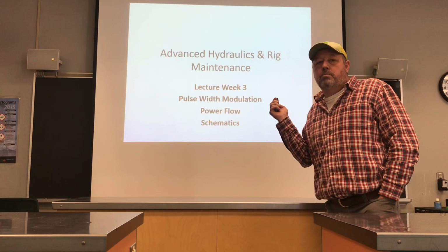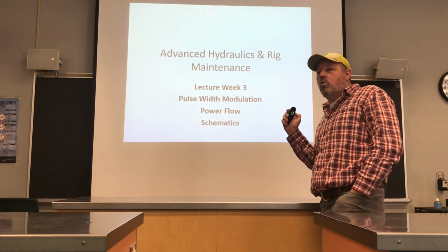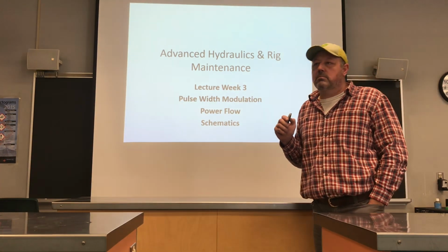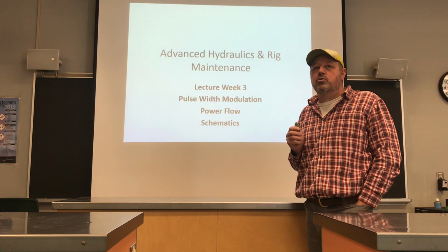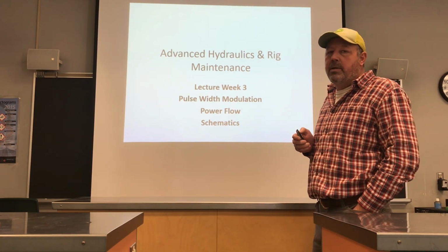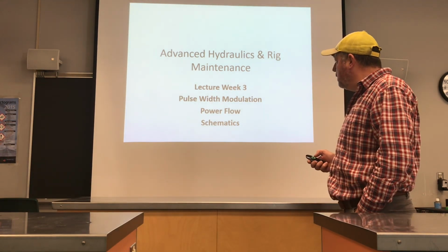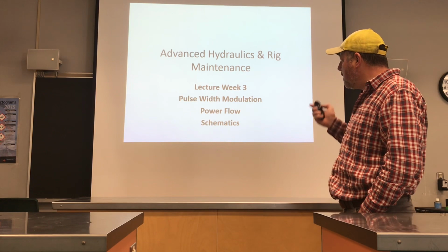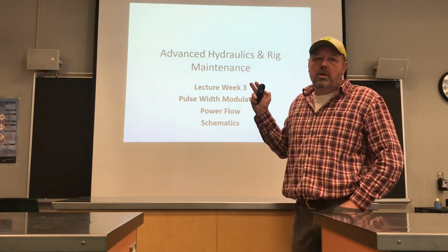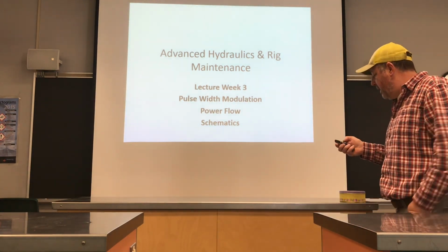Basically, we use pulse width modulation or duty cycle in order to modulate or proportionally control how fast or how slow an implement or a cylinder moves. We'll talk about power flow today, and we'll also get into reading schematics and why we have to have them.